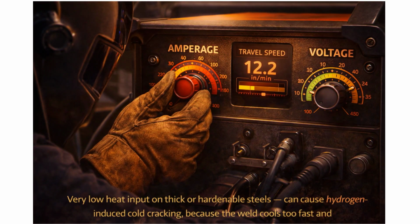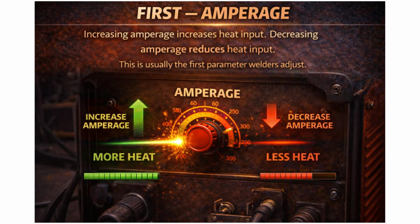So how do you control heat input on the job? You have three levers to pull. First, amperage. Increasing amperage increases heat input. Decreasing it reduces heat input. This is usually the first parameter welders adjust.